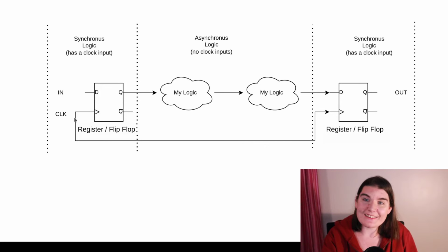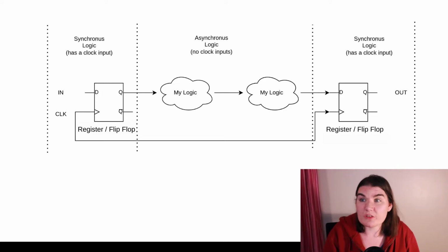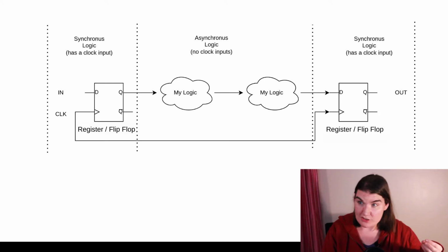And the clock needs to be the same clock to go from one memory element to another. If it's not the same clock, it's a clock domain crossing. And again, you have timing issues. You have issues with your static timing analysis. This is why it's extremely important that you use the same clock for signals for their source and their destination. Very important.